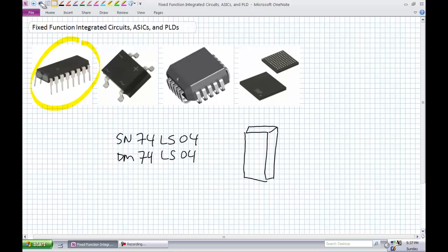They all look the same. They all look like that thing. It'd be so easy for you to grab a damaged one or the wrong one or put him in the wrong drawer. So standard operating procedures, pull it out of the drawer, make sure it's got the correct pins on it, make sure they're not damaged, check the number on it, put it in the chip checker. The first lab I'm going to show you guys how to use the chip checker, because there's nothing more frustrating than working on an entire lab and realize your chip was always damaged and never would have worked.